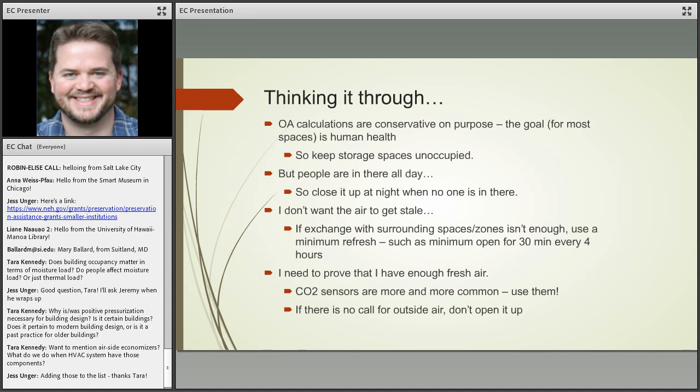It brings some fresh air in at a minimum quantity, and we get a little bit of air turnover instead of just working through recirculation mode all the time. But again, minimize it. Think about how you can control the actual amounts that you're bringing in, in the effort to not bring all that moisture into the system, into the building, all the time.